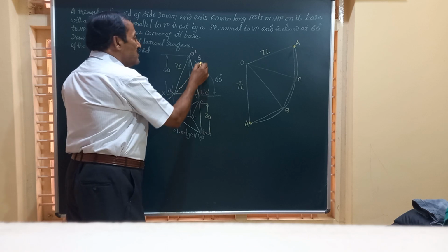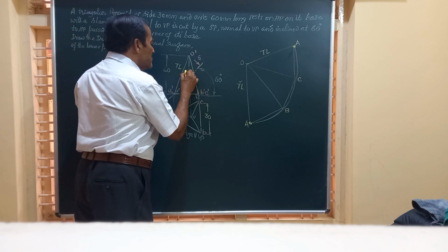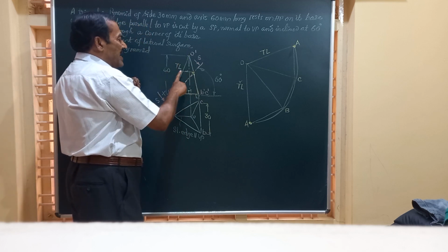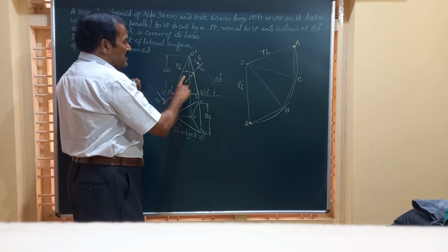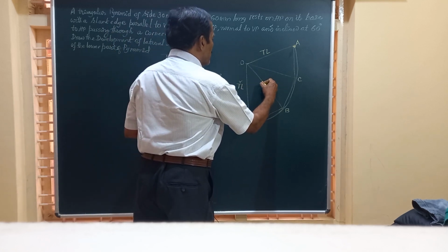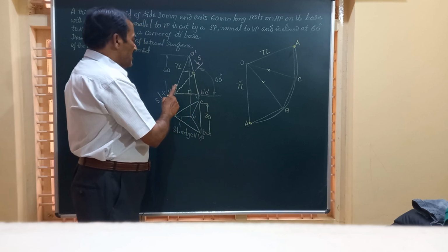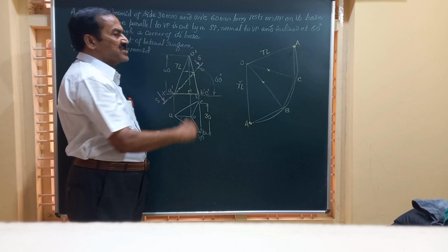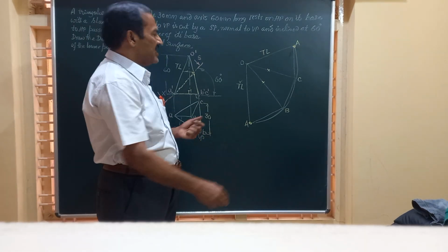This point where the section plane is cutting the solid has to be transferred to the true length line, that is O dash A dash, and mark this distance from the base on OB and OC. So from here you should take this on OB and this is on OC. And that's all. It is passing through one of the base corners and cutting two slant edges, namely O dash B dash and O dash C dash, which I have marked here.